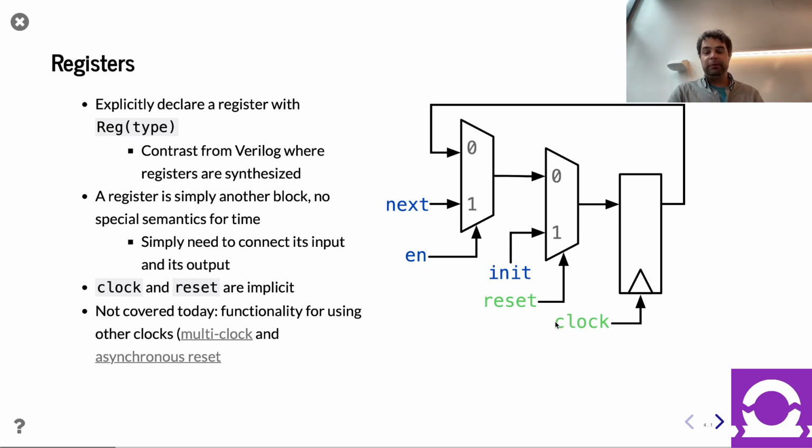Cool. And so in terms of reminding ourselves what functionalities we have, normally for a register, you have an input and you have an output on the rising, positive edge of a clock. The input is now loaded into the register, and from then onwards, the output is that value. And so every cycle, it reads a new input and puts out a new output.